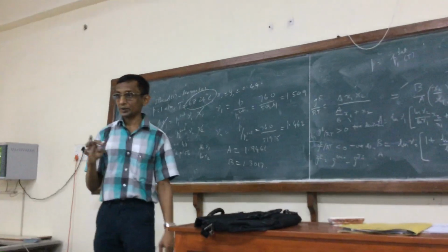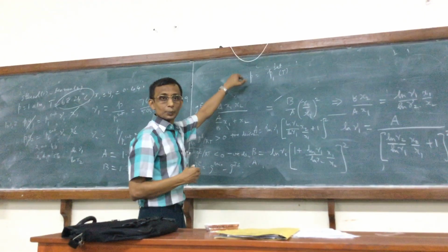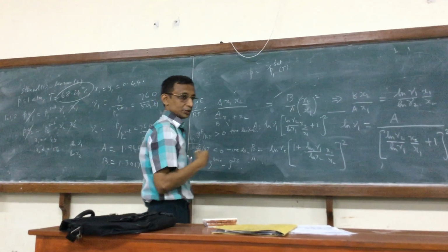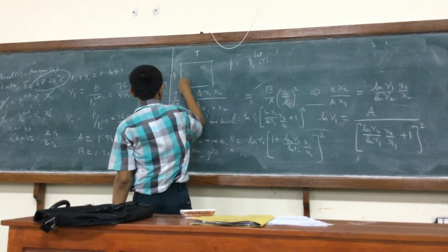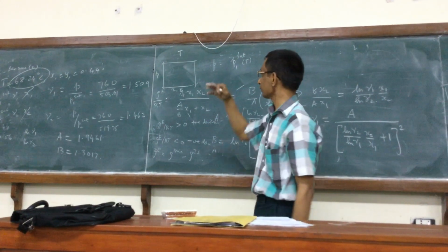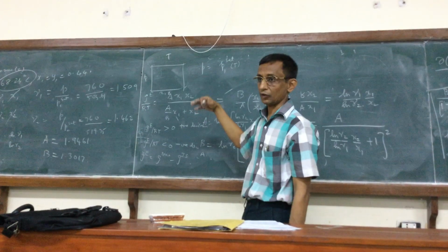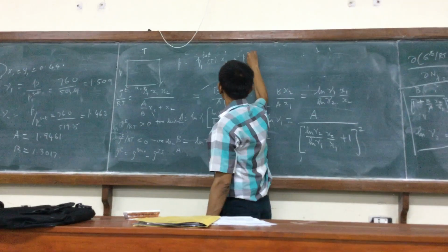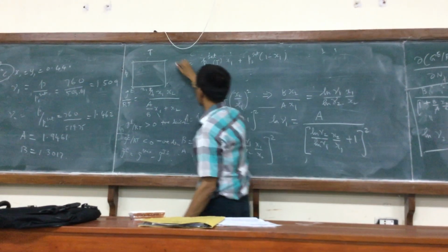So I am going to fix the temperature, and also the x is fixed. So bubble pressure would be the way P depends on x at a particular temperature. So I am looking at, at a given temperature, P versus x or y. Bubble pressure means I am looking at P versus x. P versus x is actually going to lie above the P versus y curve for the pressure. That is a characteristic feature.